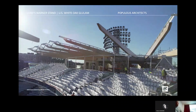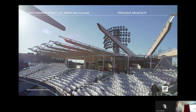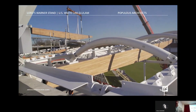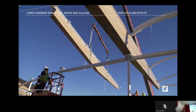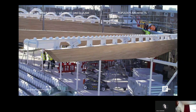So, after a lot of research, they settled on utilising American white oak. Again, European oak was considered, but because of the better strength class and the straighter grain of American white oak, they went with that species.